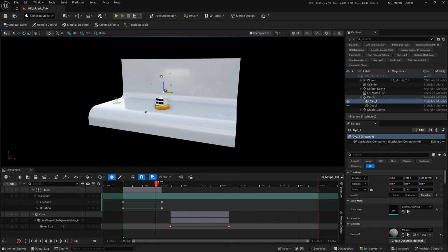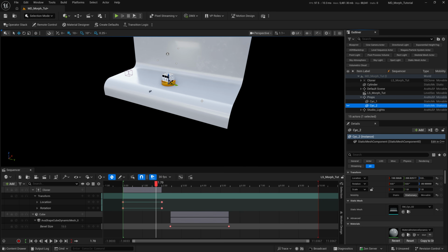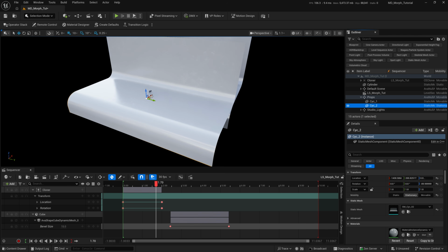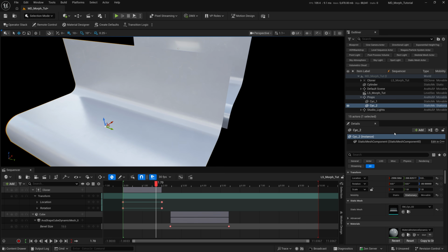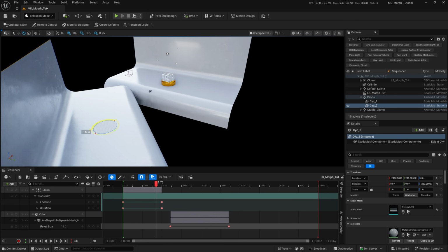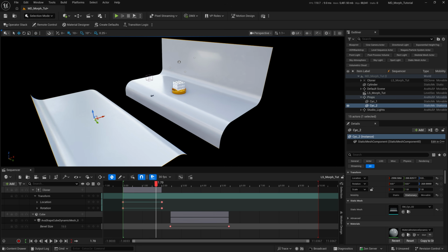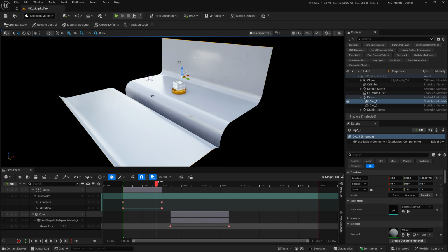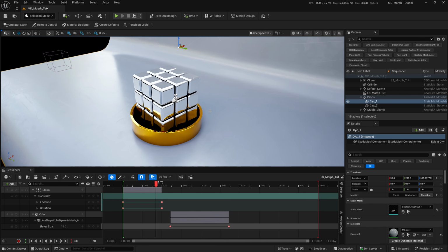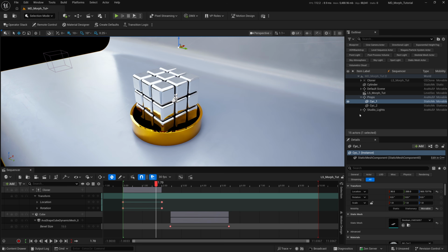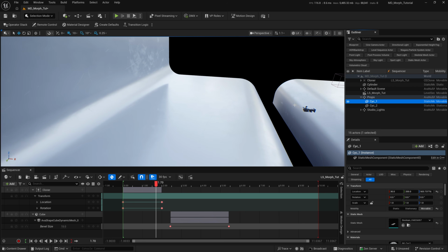So what we're going to do is I'm going to take site number 2. I'm going to pull it out. Enable that, right? Pull it out. And I'm going to rotate that 180 degrees. So let's rotate that around and let's push it back forward, something like that. And if I go back to my bookmark, you see now the reflection is not there anymore, right? That's the reason why we have 2 of this.